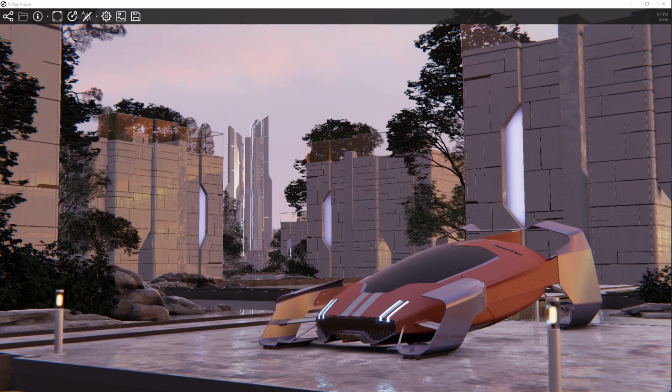Also, note that when you have the automatic IBL sun option enabled in the Vision settings, Vision will automatically add a directional light based on the brightest spot in an HDR image you're using to help you get a more accurate lighting preview. However, this option has no effect if the project sun is enabled, and it is not recommended if there is no single distinct bright spot in the HDRI used for lighting.